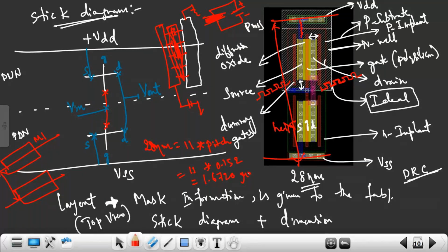So a standard cell is nothing but all the gates where the height is fixed based upon the technology node. 28 nanometer is 1.672, and for 40 nanometer the height is different. Height will be calculated based upon how many routing layers you can allow, and based upon the power rails and VSS rails. We consider a few parameters for fixing the height of the standard cells. But coming to analog, this is not true, where width and W by L ratio keep changing. If height is fixed, those cells we call standard cells.